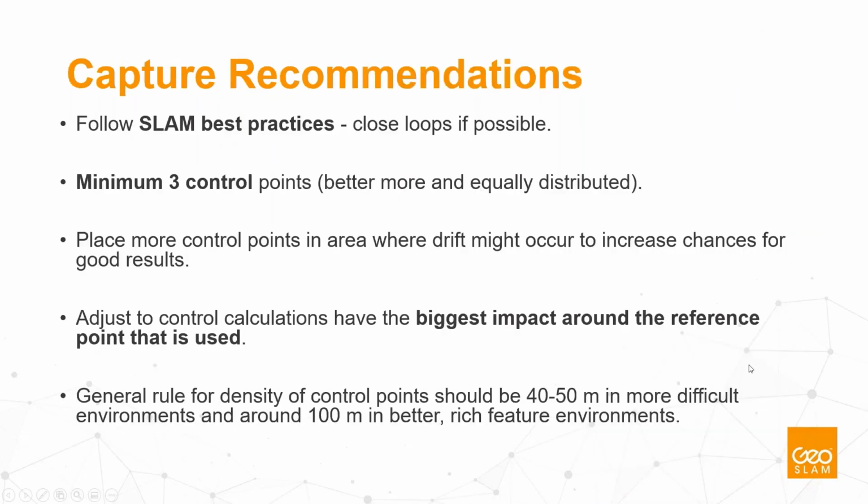Couple of recommendations that I wanted to mention. Definitely, we are still recommending and stressing that the SLAM best practices have to be followed. If it's possible to close the loop, close the loops and follow all of the best practices. This feature is not going to be able to correct any major bigger drifts. It is there to produce a georeferenced point cloud and correct some part of a global SLAM. I will get to the processing stage in a second as well.